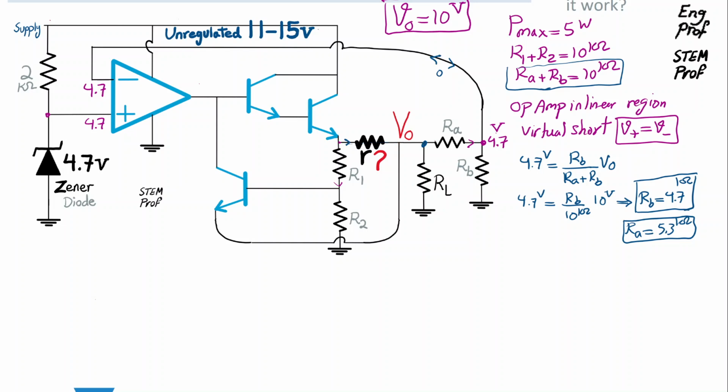But if the load becomes too small, so if we, for example, reduce the value of RL too much, it tries to draw a considerable current from the transistor while keeping Vout at 10 volt, and then at some point the circuit would not tolerate that, and that turning point is defined by this combination here when they turn on this BJT current sensing transistor.